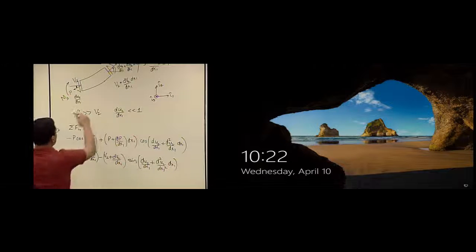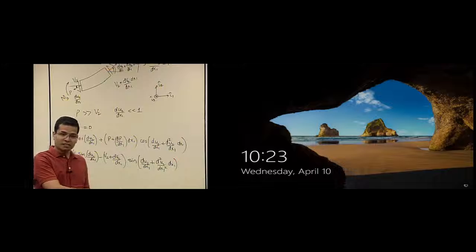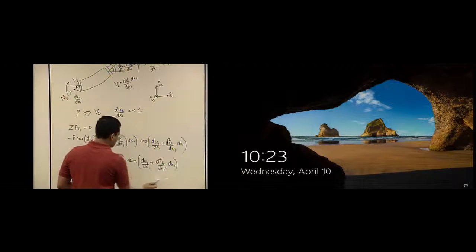So in the bending free body diagram, you do not see any axial loads because we decouple them first. But in this case, a large axial compressive load is causing bending. So we cannot decouple the two, even if it's applied at the centroid. So the key thing is that now there's a large axial compressive load causing bending. Yes. So that's why we have these components.